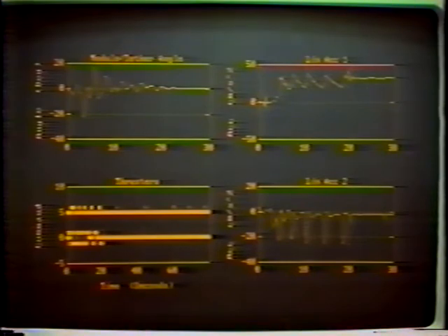That would be a lot smoother if a constant thrust were used during the tether deployment, or a finer control algorithm with a smaller pulse width. These are results from a computer simulation that I will describe next in my talk. The blue lines that you may be able to make out there at right angles to the tether are lines that are fixed in the body axes of the end modules, and the red coming on indicates a thruster firing in opposite directions on the two modules.